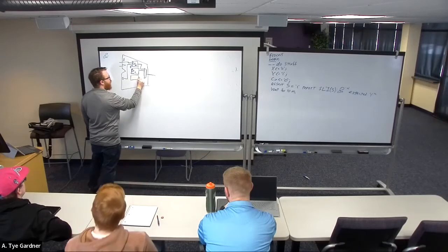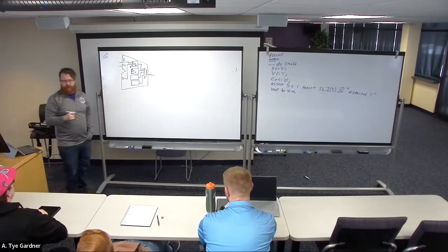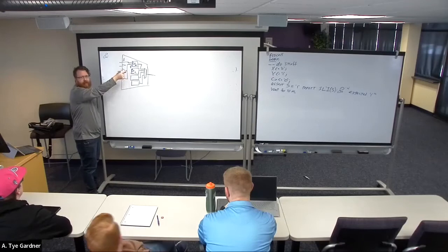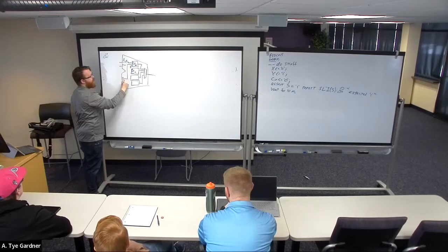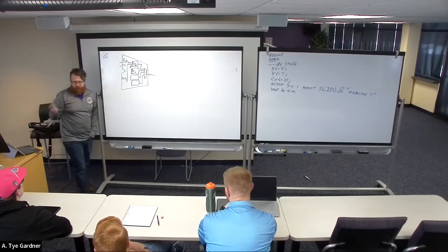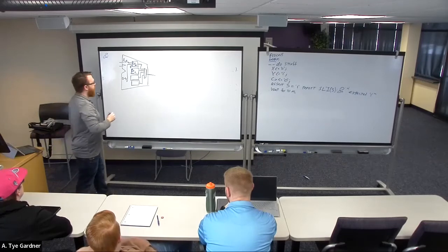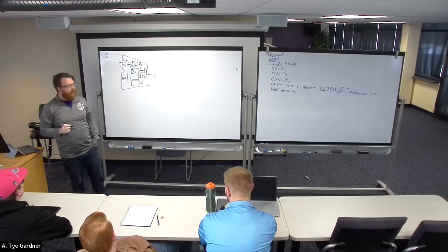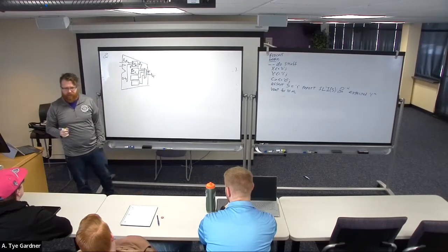All right, it's gonna look something like this, right? A couple of internal blocks. We've already designed the adders, or at least we'll have, they're gonna be 8-bit adders. So A is going to be 8 bits, B is going to be 8 bits. If I add two 8-bit numbers together, how many bits is my output? 9 bits. So that means this is going to be 9 bits. That means my output, which we're going to call R, is going to be 9 bits.